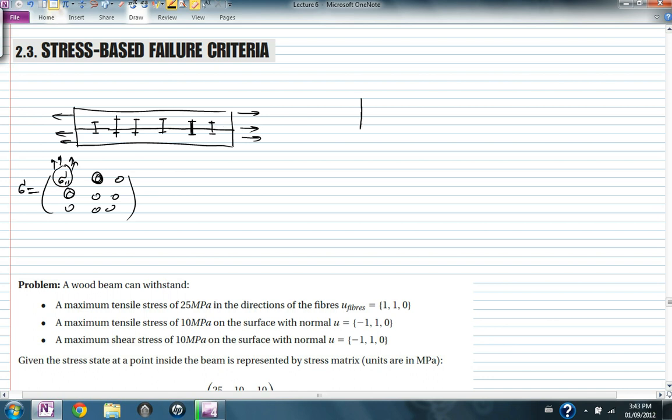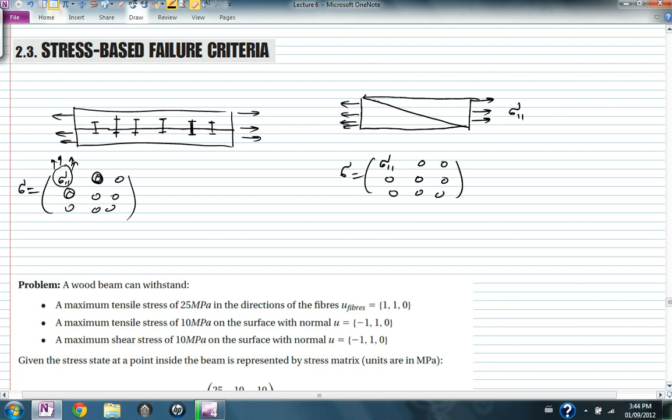On the other hand, if I apply sigma 11, where the stress state is made out of sigma 11, 0, 0, and I'm worried about this particular plane, and it's a weak plane, and I'm using some shear studs to protect this plane from shearing. Now if you actually calculate the shear on this plane, first you have to calculate n, and then calculate Tn, which is equal to sigma transpose n, and then you calculate the shear stress.